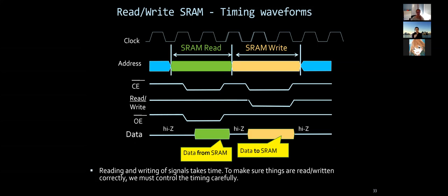This is the minimal timing that allows me to reliably sense the change in your circuit, right? Essentially it's the same story here. The changes of the value start much faster than the standard time, but I need to make sure it's done reliably. That's why there are fixed latencies associated with SRAM. And again, you're going to see that there is a latency associated with the cell itself.